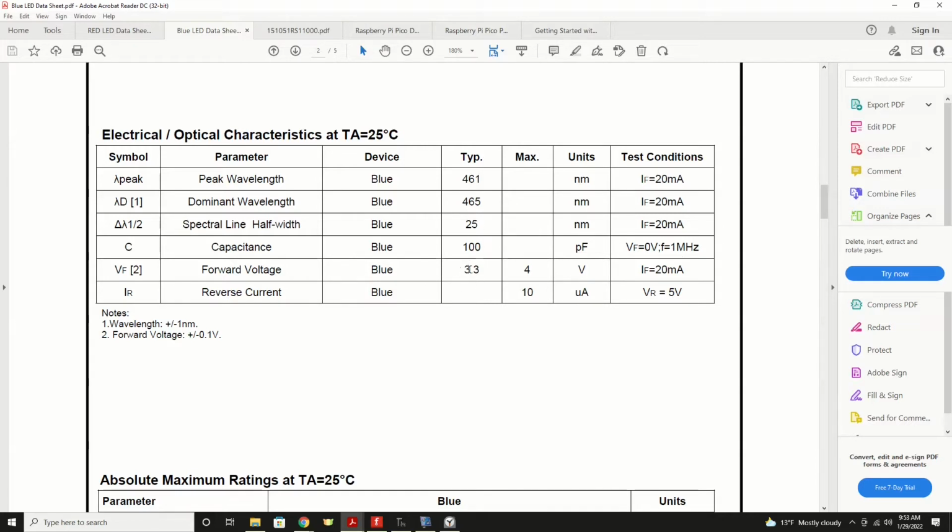And that's the key element for figuring out what resistor we need to limit the current that we're putting into the LED. Not all LEDs have the same forward voltage. So that is why we have to look at the data sheet rather than just guess. Now, over the years, many tinkerers in electronics have come up with a very simple rule. And that is, if I use a resistor of somewhere between 220 and 330 ohms, I'm going to probably be okay, and the LED will be a little on the dim side. And in truth, that will work for 5 volt electronics and 3.3 volt electronics.